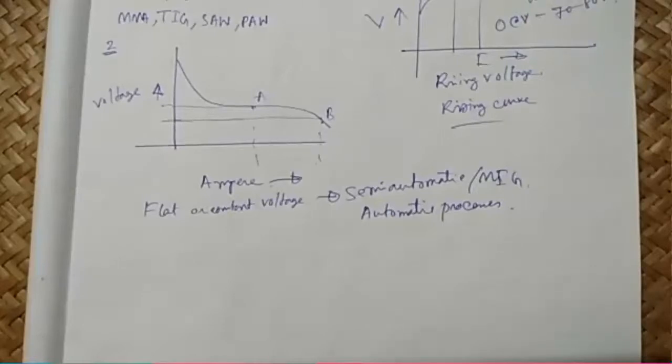Please try to remember this point. We do not change any DC current. Whatever we need to change in the current characteristics, we change it in the AC portion before it reaches the rectifier. When it goes to the rectifier, the current is fed or used for welding.